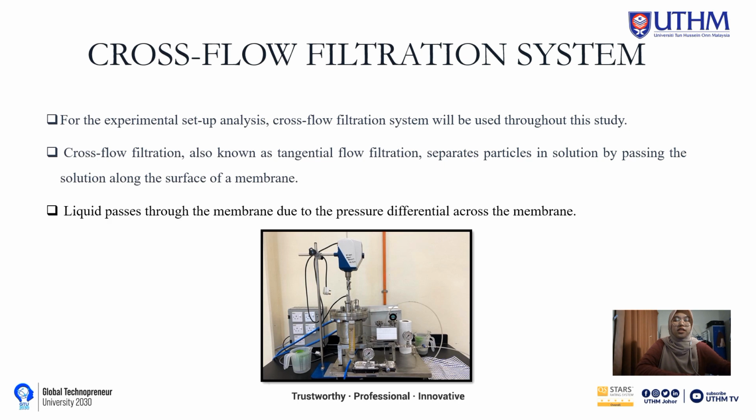For the experimental setup, a closed-flow filtration system will be used throughout the study. Closed-flow filtration, also known as tangential flow filtration, separates particles in solution by placing the solution along the surface of a membrane. Liquid passes through the membrane due to the pressure differential across the membrane. Closed-flow systems are configured to allow recirculation of material along the membrane surface. In this way, large components are retained and smaller components are collected in the permeate.